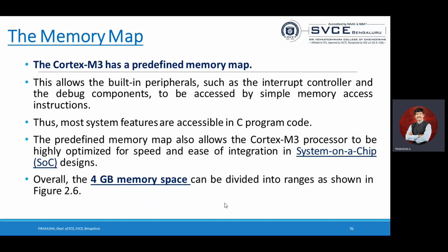This microprocessor cannot run the C program as it is. It needs a hex code only. So you need to convert that C program into hex code, and that hex code has to be dumped or burned into the hardware. Then the program is going to be executed. It will execute and run the peripheral device that you have connected over there.